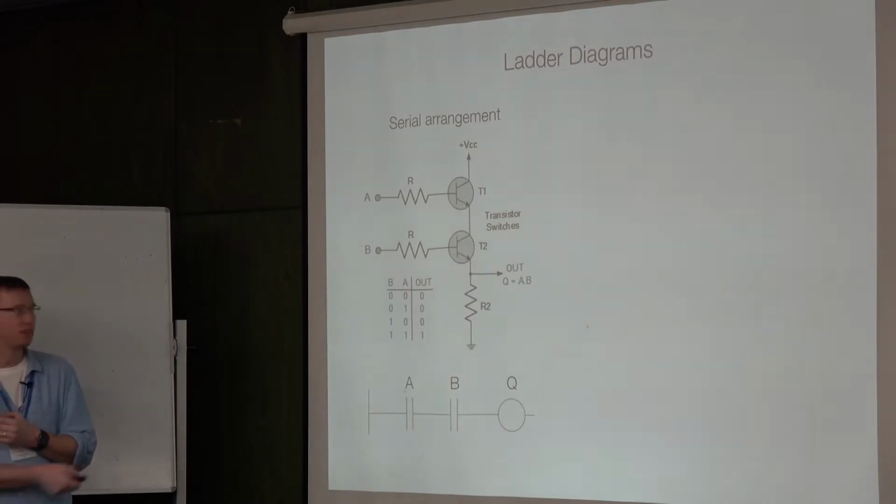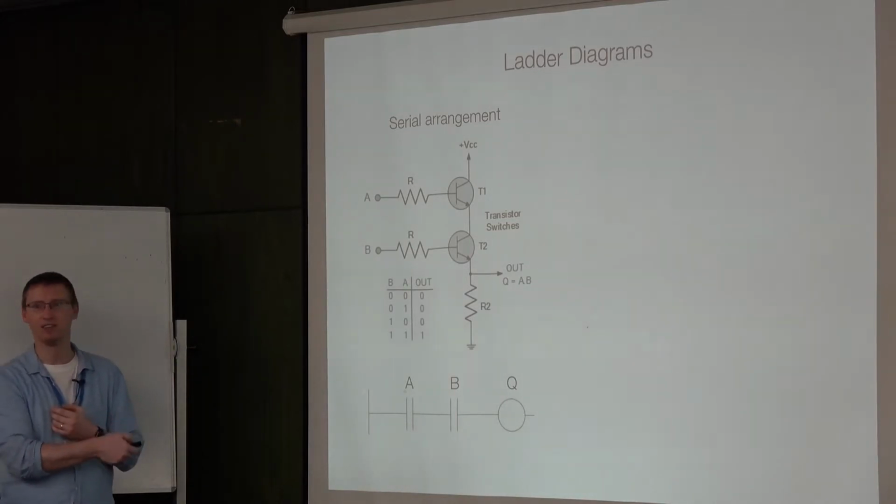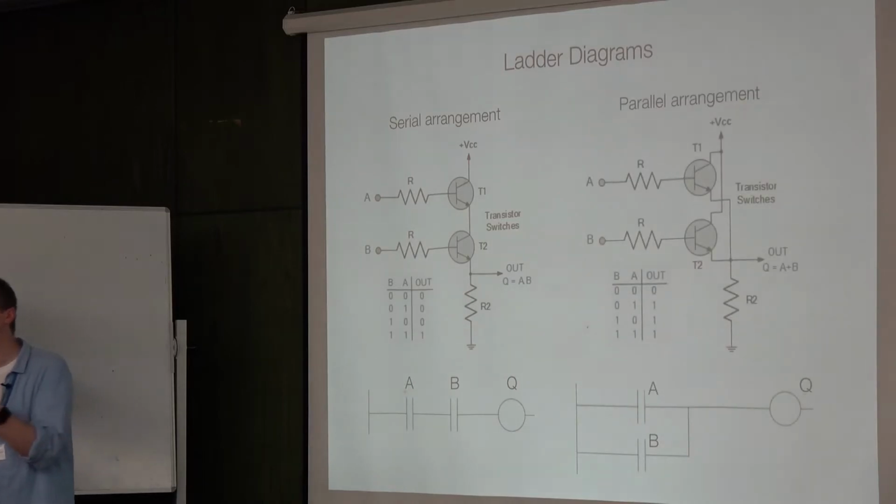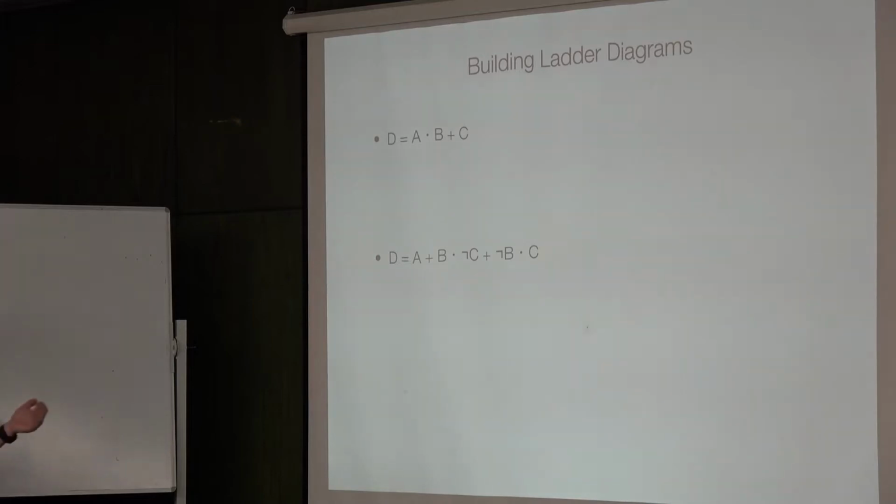Okay? And of course electrically we can realize it like this, but the power of PLCs is that this is really freely reconfigurable. So we can as well graphically assemble more elaborate switching conditions, like if we put them in parallel, then we suddenly have the Boolean summation of those two inputs. So switch on the machine either if the gate is closed or when the safety switch is on, something along those lines. Okay? And of course, it doesn't end with those kinds of simple AND or OR arrangements. We can put them together, right?